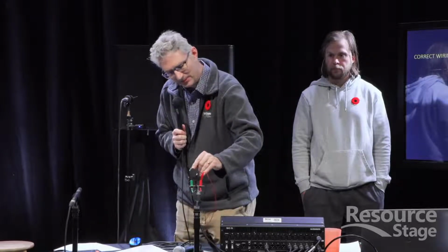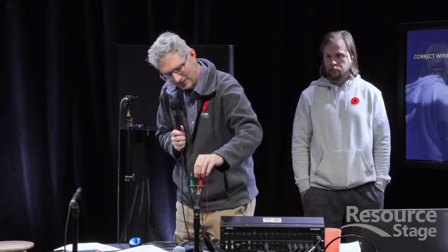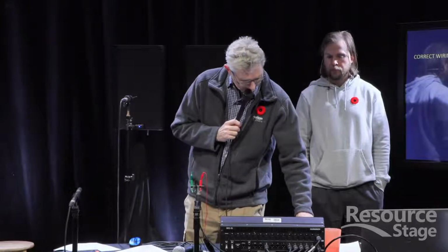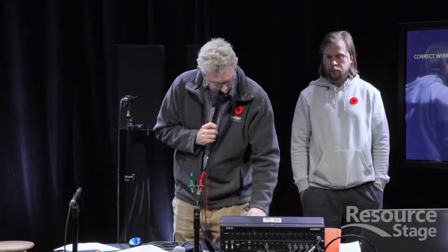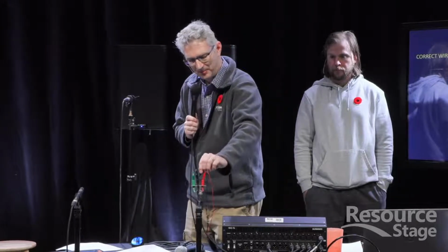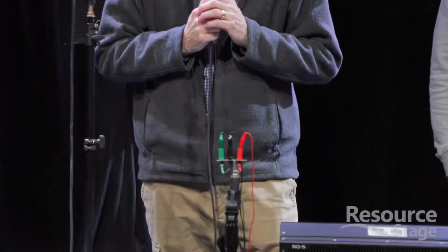Now, what's going to happen if one of the other pins is broken? I'll put that one back, disconnect this one and unmute. And now? I'm turning up the level here. Oh, I can hear a little bit. Yeah, there's a little bit there, but it certainly is a lot thinner and not nearly the level. I've got the faders up all the way on my mixing console, and there's only a little bit. It's the same if you've got pin 2 broken. It's a low volume and a thin sound.